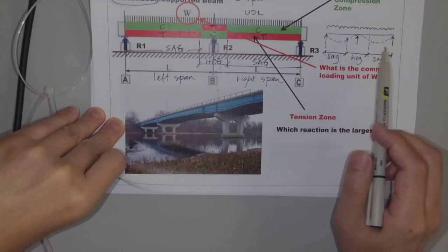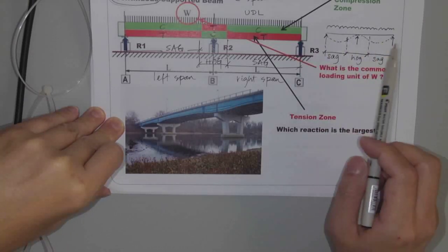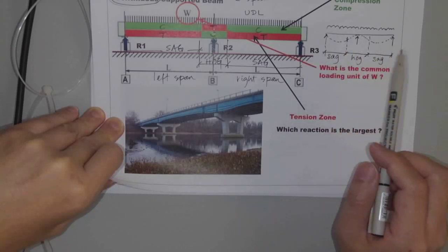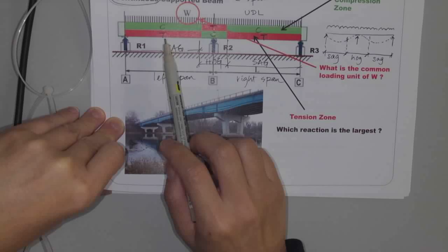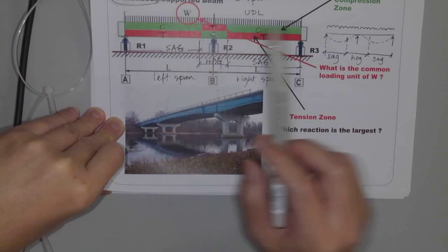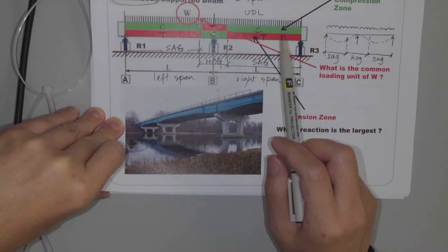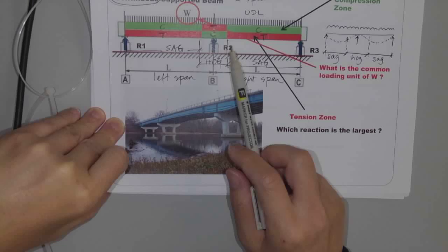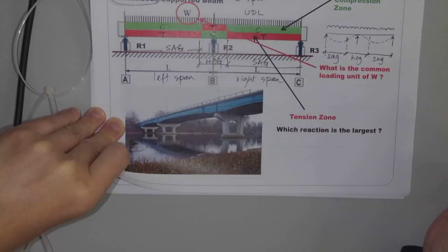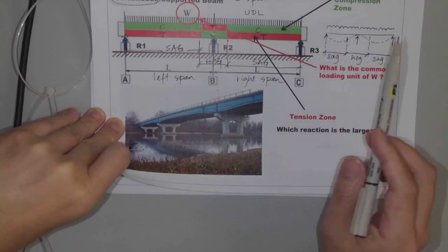And from this, we divide the beam into a few parts, and part of them are in sagging and another part in hogging. And from that, we can tell which part is in compression or tension, right? And actually, in last week's in-class exercise, there were also one or two questions about those deflected shapes. So you should be able to sketch those things.